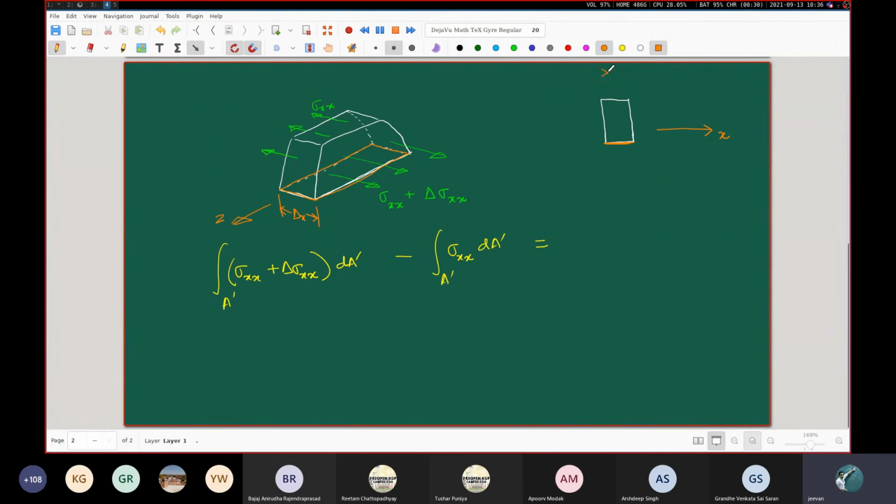So this is our x-axis. This is our y-axis. Now we are talking about this bottom surface because we are talking about this bottom rectangle. So there, the unit outward normal is along the negative y-axis, which means in order to maintain the positivity convention, if I want to write this tau, for the first subscript I have minus y, and the second one is minus x.